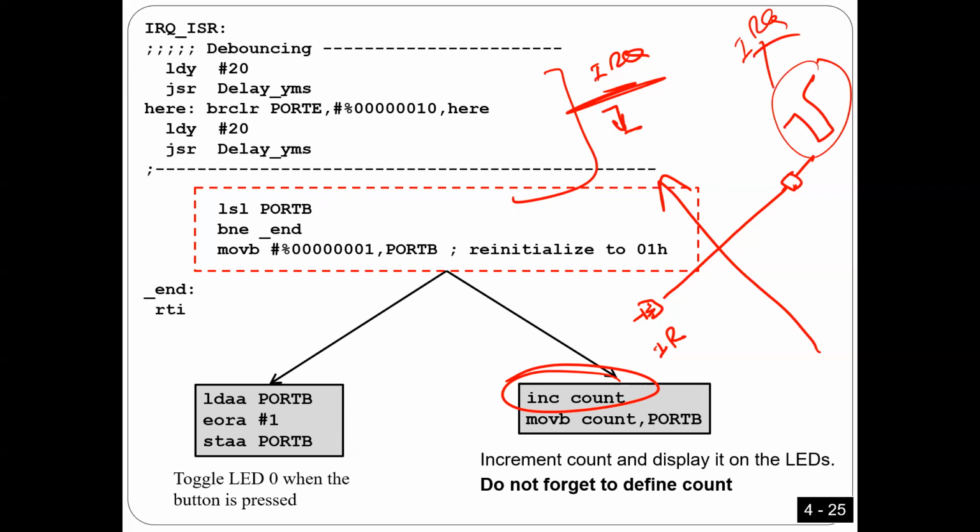You get what I'm saying? So every time I receive a pulse like this one, that means one customer enters the store. So if I want to count the number of people who enter the store, all I need to know is how many interrupts you got. That's it, because every interrupt means one person. You got what I'm saying? So all I have to do here, guys, is that every time there is one interrupt, I'm going to increment a counter. Then I can display this counter on port B, or on the 7 segment, as I'm going to explain later, or on the LCD, wherever.